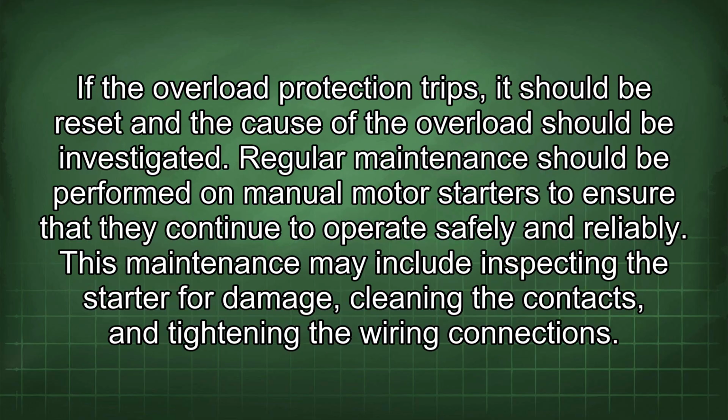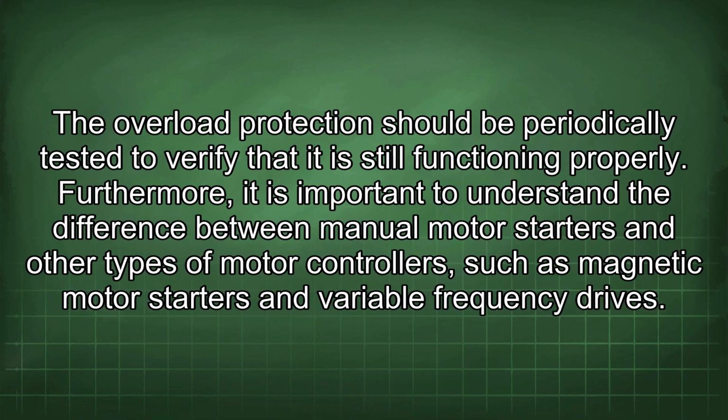Regular maintenance should be performed on manual motor starters to ensure that they continue to operate safely and reliably. This maintenance may include inspecting the starter for damage, cleaning the contacts, and tightening the wiring connections. The overload protection should be periodically tested to verify that it is still functioning properly.